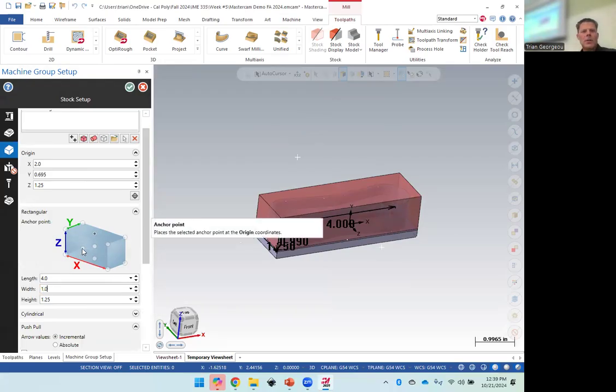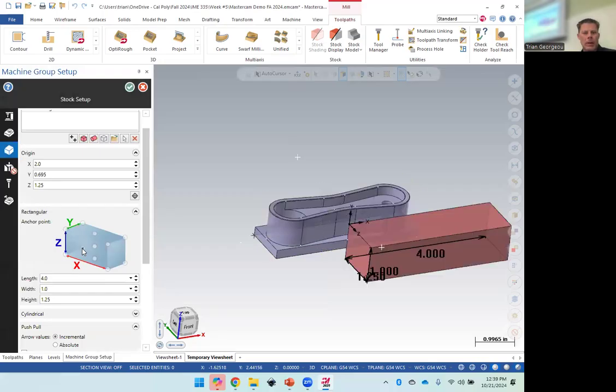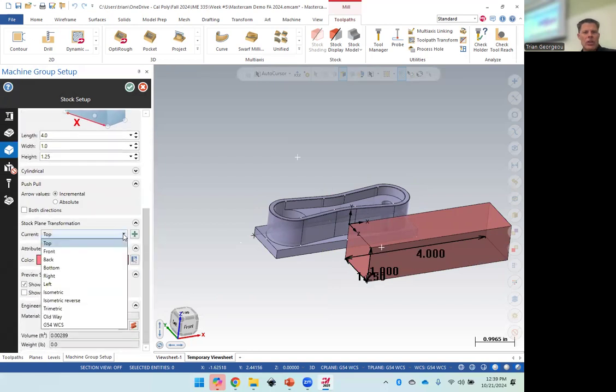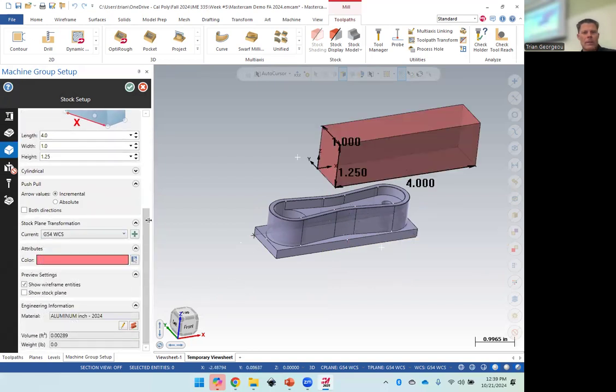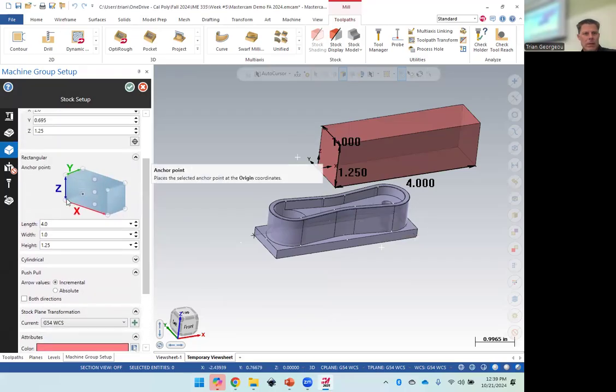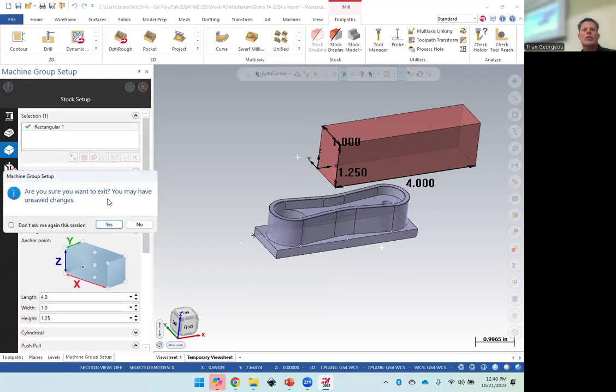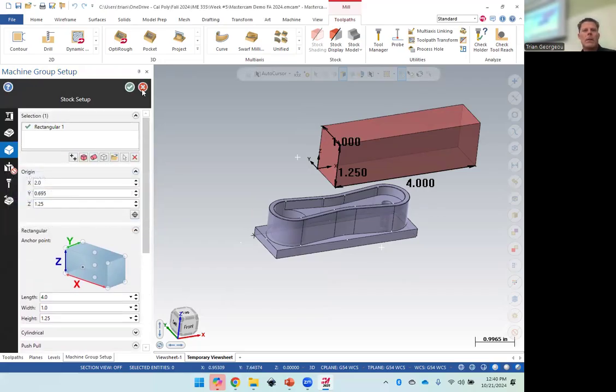1.0. Also, I want to be in this bottom left corner. Hold on. I messed that up. I want to be on my G54 work coordinate system. Hold on. Off that corner. And I want 0, 0, 0 up here. I messed that up. I'm going to press X and show you it from default.